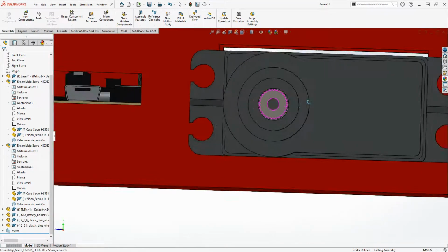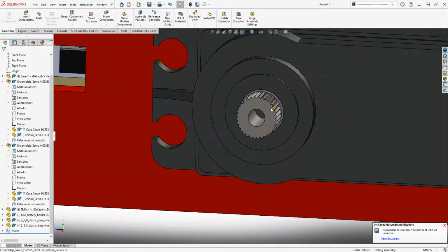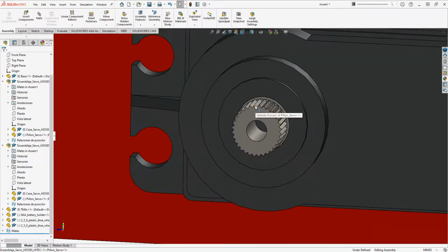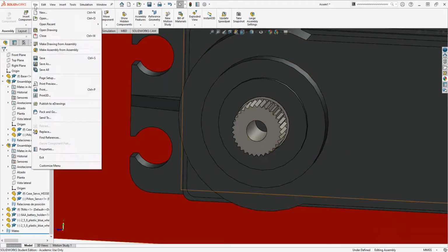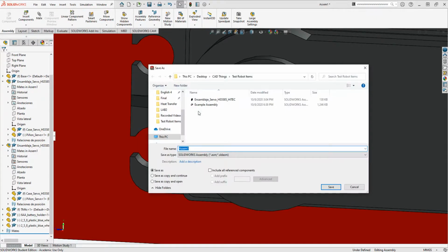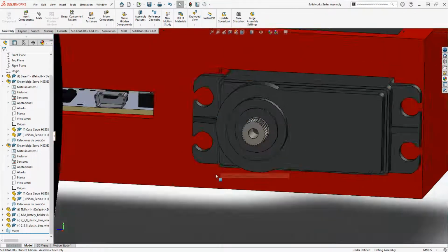Now a little thing right here is, let's readjust our camera angle. It always helps. It's at a weird angle, so we can always fix that. We could rotate it for hours, but that's where mating comes in. It's very helpful. I'm going to take this plane and this plane. We don't want to orientate it so they're coincident planes, we want parallel planes. And honestly, that just makes everything easier. Now I can move it around and put it into place.